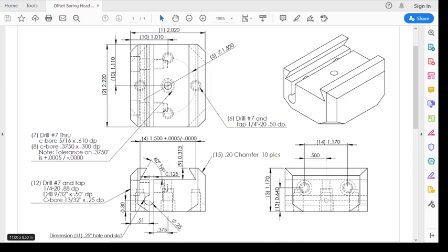Basically, we have a chamfer on the top, these front and back edges, and then these corners. So what I can't do is say this is chamfered and chamfer that at the same time. What I have to do is chamfer these 3 sides or 6 sides, because it's on both sides. I have to chamfer this, this, and this, and then in a second chamfer, add this chamfer onto here.